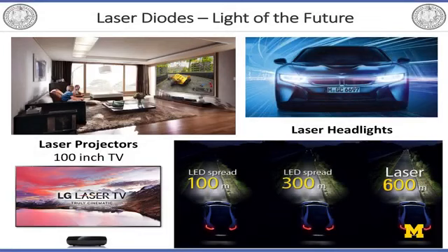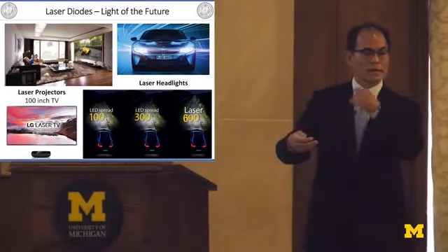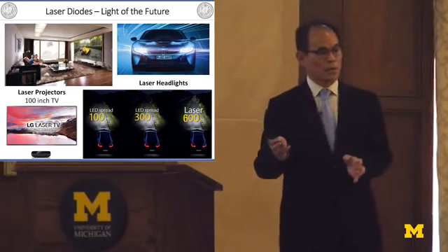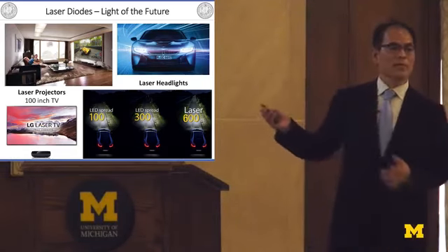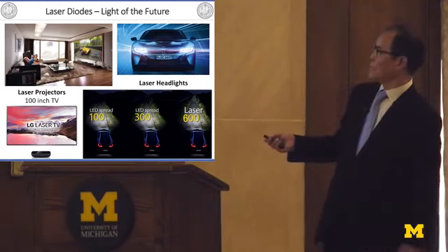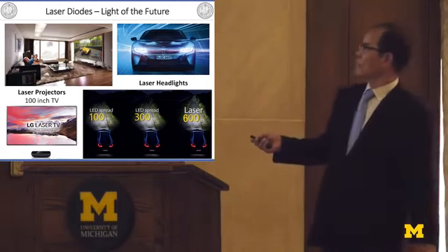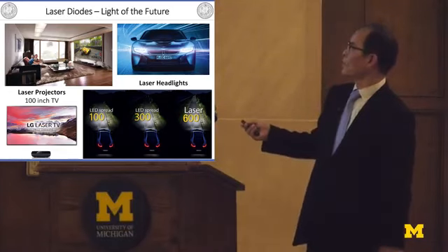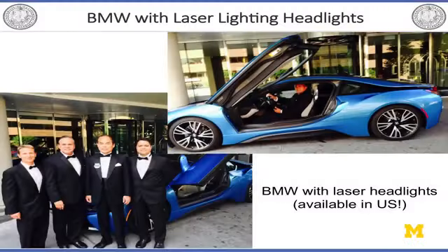And also automobile headlamps, they already use laser lighting. This blue laser diode excites phosphor to make white. The advantage of laser lighting is the irradiation distance: it was 600 meters, now it's 1 kilometer. Up to 1 kilometer we can irradiate. So it's very safe. In Germany, they have the autobahn, so speed is so fast, they need this laser lighting for safety. LED is only 300 meters, and conventional lighting is 100, it's small. So this is very important for safety. Already BMW and Audi use a laser headlamp.